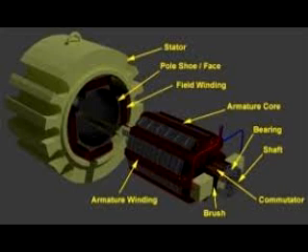Some drawbacks are that shunt wound brush DC motors are more expensive than permanent magnet brush DC motors and have the potential of motor runaway if the shunt current decreases to zero. This is a very dangerous condition that can lead the motor to literally break apart.